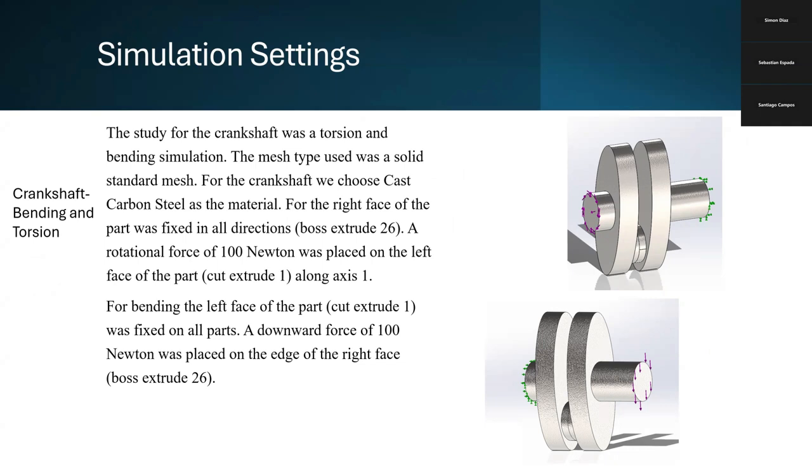For bending, the left face of the part was fixed in all directions. A downward force of 100 newtons was placed on the edge of the right face.